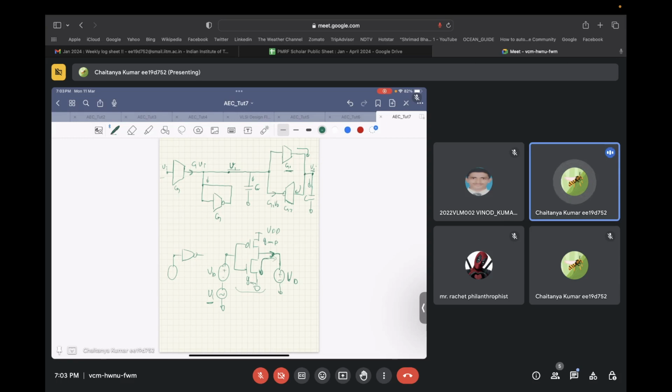There will be some quiescent current that will be flowing, that we calculated just now based on the self-biasing condition of the inverter. And on top of that, when an incremental voltage is applied as VI, a small signal current will be sinking in, that will be GMN times VI into the NMOS, and there will be some current sinking in, that is GMP times VI into the PMOS.